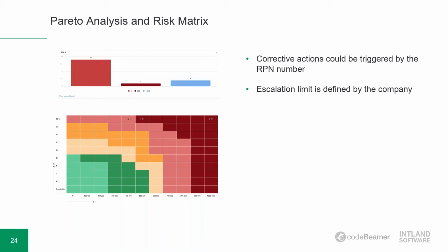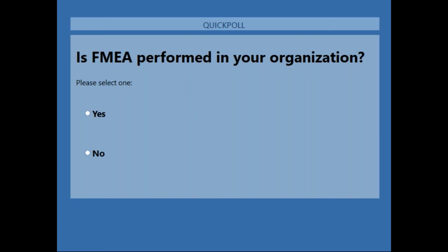Most likely, I will not be able to minimize this risk completely, so I will need to have detection actions, which are typically different types of testing. For example, functional testing, lifetime testing of the design, end-of-line testing during manufacturing. Of course, you can have integrated detection mechanisms, which are actually your safety concept. Of course, the testing methods are given in the standards that you are using. So these should be included in your VMV plan.